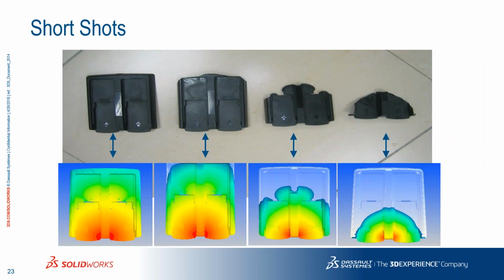Short shots: if you make thinner and thinner parts, which is the trend in many industries, you could end up in a situation where the plastic will solidify before it fills the whole cavity. And it's important to understand if and how you can fill a thin part.